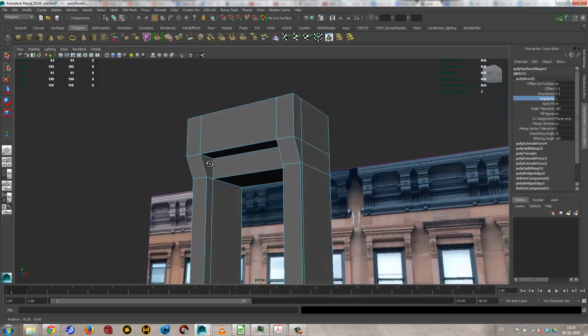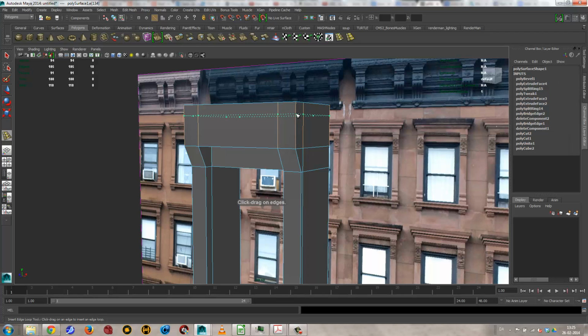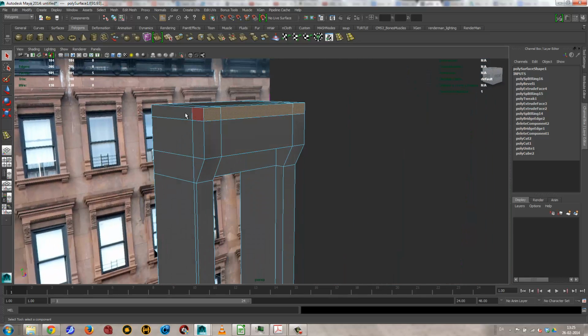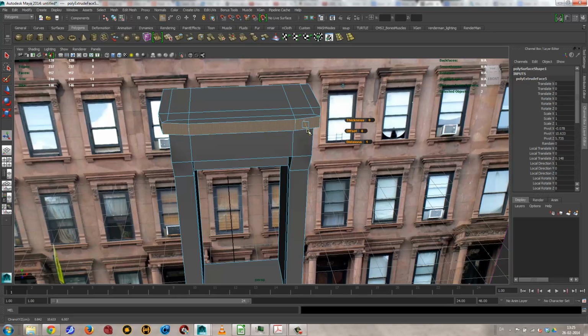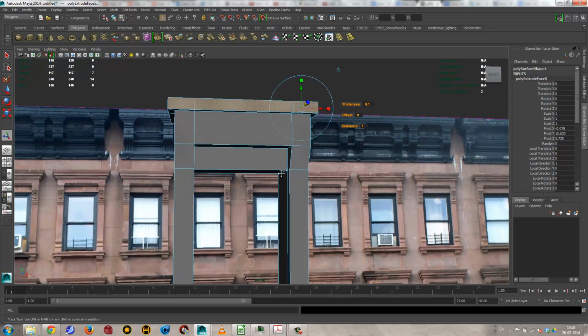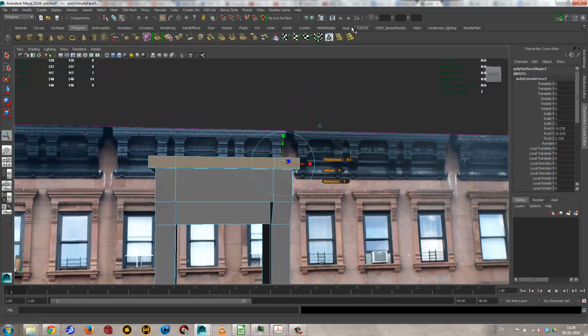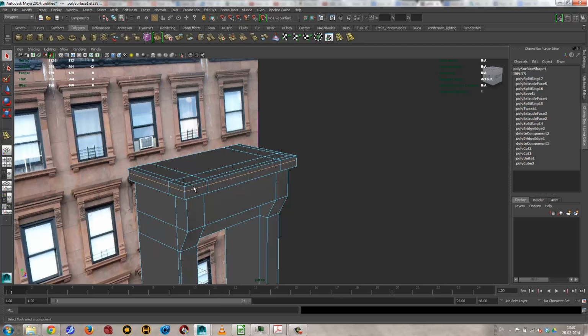And then this thing up here, if I wanted an extra edge here, I can just add an extra edge loop, and then perhaps grab the faces going around here, and extrude that like so, perhaps. This can sometimes happen if you drag the blue arrow. Then you can also use the thickness, so that will come out straight like so. And of course this depends on how much detail you want to add. So at some point you'll just say, okay, this is fine.